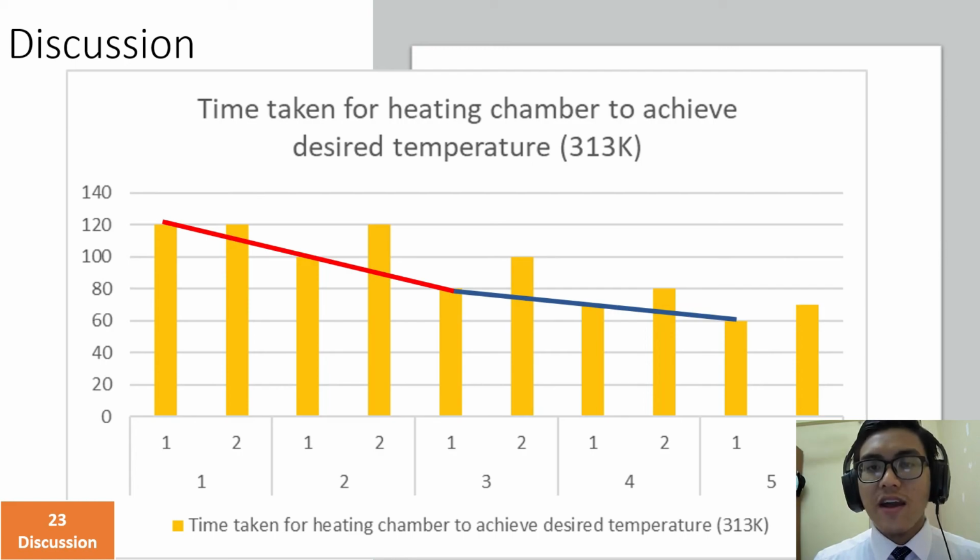Although case 5 has the shortest time, it is not the best because high air velocity will cause the airflow inside the heating chamber to be too fast and will prevent the sludge from heating up and evaporating during the drying process. Hence, it will reduce the drying rate of the sludge.